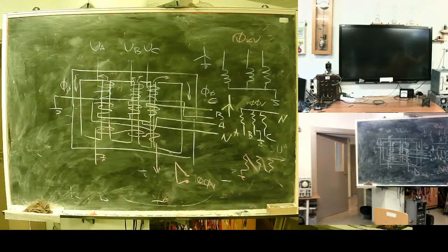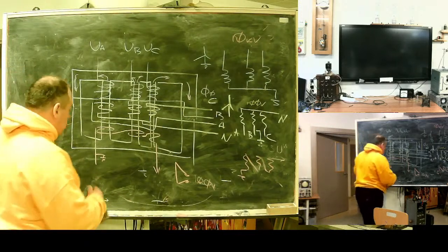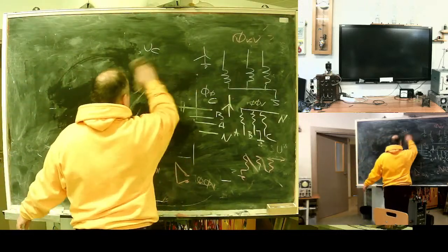This thing is precise, so for metering it should be installed. But in a very typical design, you have 2 busbar systems with an interconnecting switch, 14 kilovolts for example, and 2 voltage transformers, one for each of the busbar systems. Other voltages, line voltages, are taken with a capacitive divider.